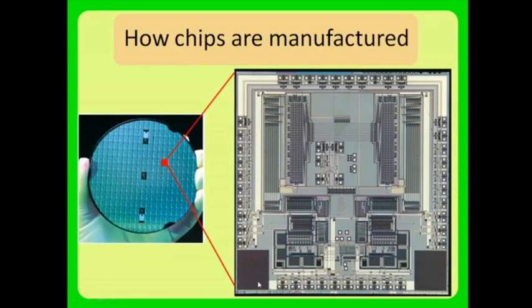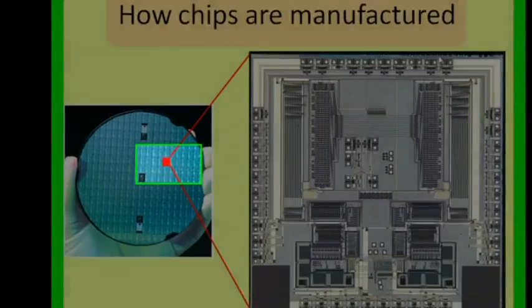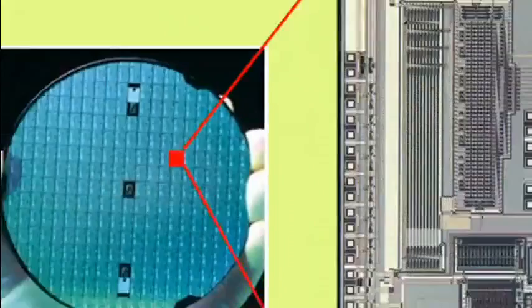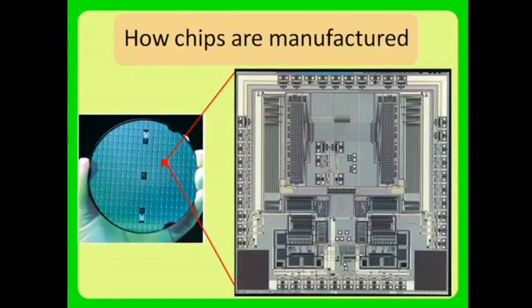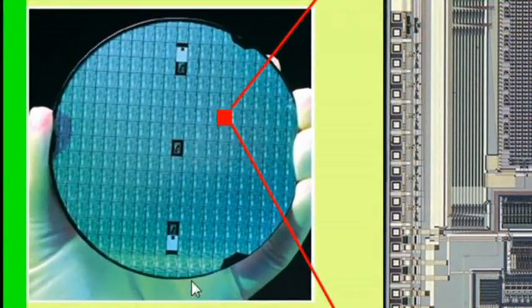This is actually a photograph at a very small scale of one chip that would be probably about the size of a pencil eraser, certainly not much larger than that. They're grown on a wafer of silicon like this that's processed with various chemicals and various kinds of photographic materials called a resist, that is some sort of a coating that resists the etching of acid, leaving certain areas exposed so they can be etched, and multiple layers built up on this sort of a slice of silicon here.